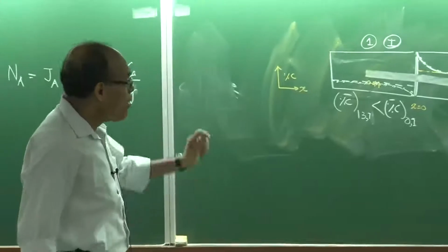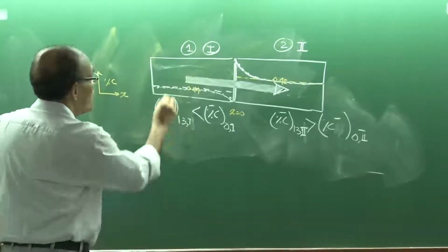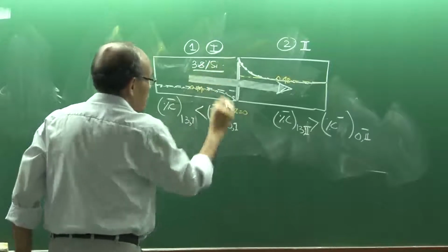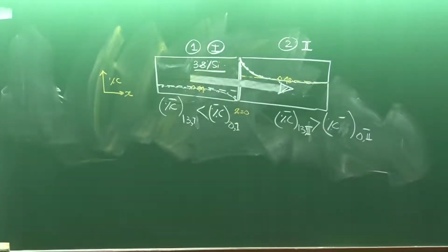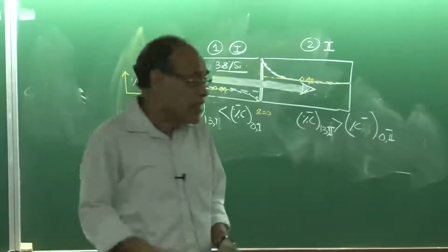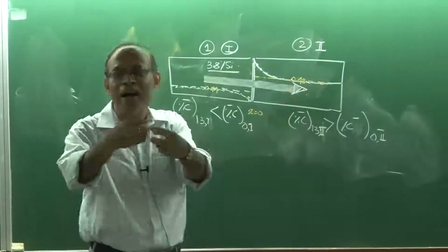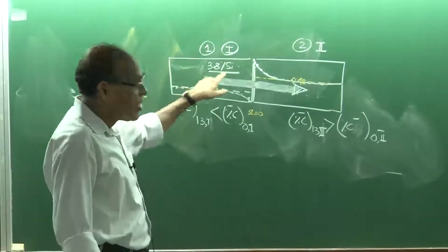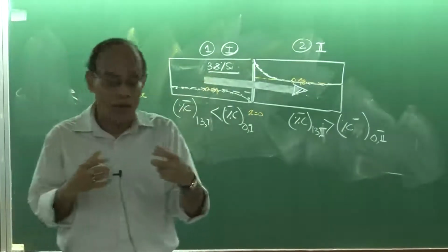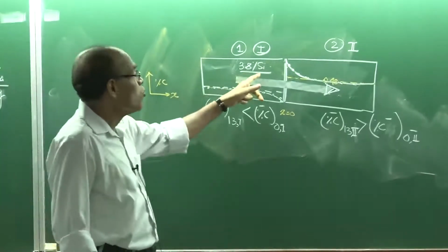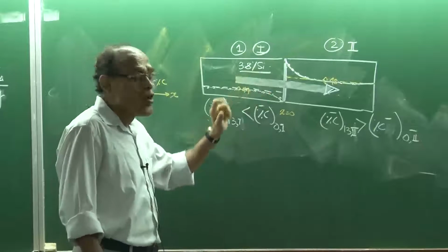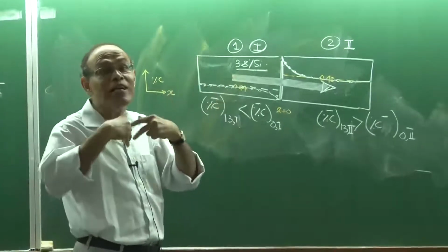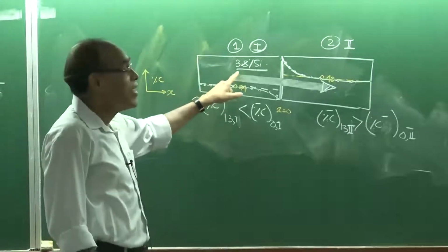Now, why does it happen? You remember that, as I said, this contains 3.8% silicon. Silicon increases the activity of carbon. So this is now a multi-component system. This would be a two-component system, carbon and iron. Iron and carbon have strong affinity with each other, so they form a strong bond. Now, the moment silicon comes, iron-silicon bonds are also quite strong, iron silicide. Iron has an equally strong affinity for the silicon atom also. As a result, in the presence of silicon, the carbon is not very comfortable. It wants to leave the system, and the activity of carbon is actually increased.